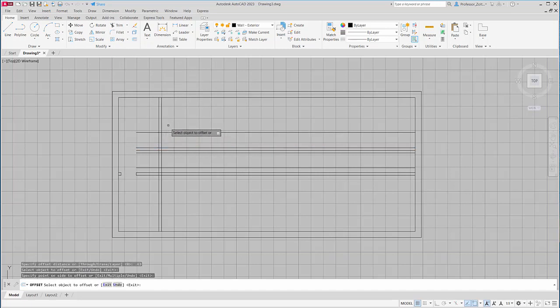From here to here. And then the thickness of that wall, like all interior walls, is 0.11. And then I've got a number of different sides, but what I'm going to do is just make the wall that's on the other side, and that's 1.98 meters. So I'm taking all these numbers right off the drawing. 1.98. And then it is 0.11 thick, 0.11, enter.